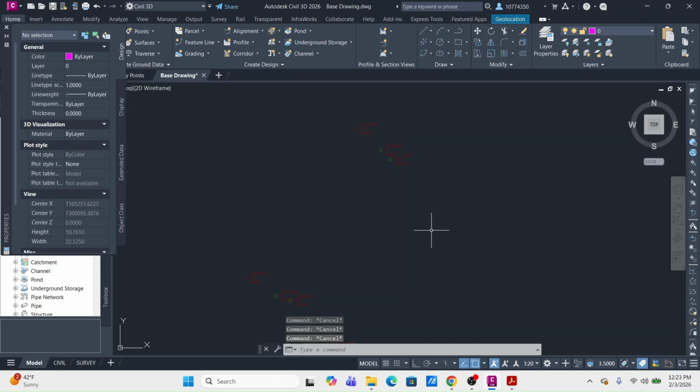And like I said, I'm going to be using these polylines for my existing surface. Each one of these survey points has an elevation attached to it. So if we zoom in here and look at this TBC, we can see that it has an elevation of 4,538.49. So when I take this line work, throw it in, and start doing existing surface stuff, it'll create elevations based on where I selected on my survey point here. So what I'm trying to get across is polylines are really useful, really great. But when it comes to creating an existing surface, this is literally a game of connect the dots.